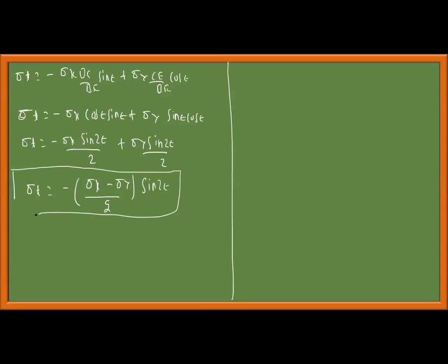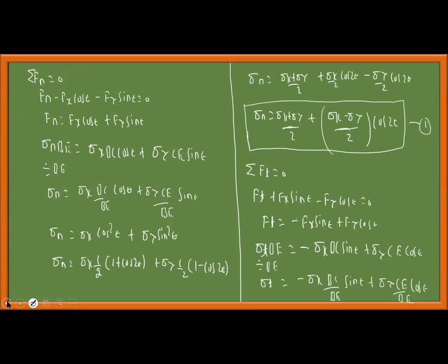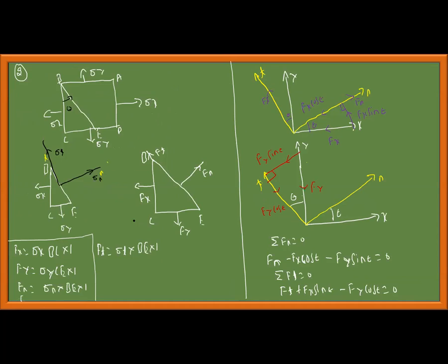This is the normal and tangential stress acting on this plane. For any body, the stress acting perpendicular to the surface is the normal stress, and parallel to the surface there is a tangential stress, also called shear stress. I got sigma_n and sigma_t, which are nothing but sigma and tau.